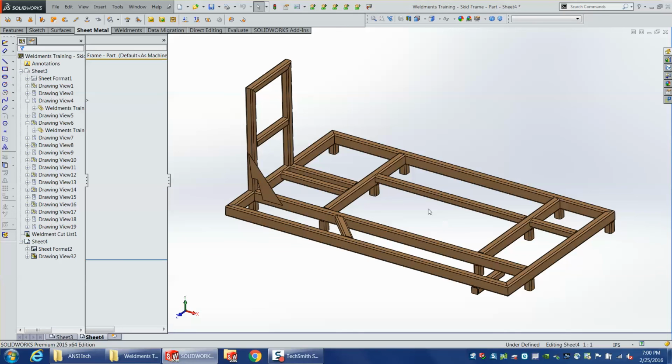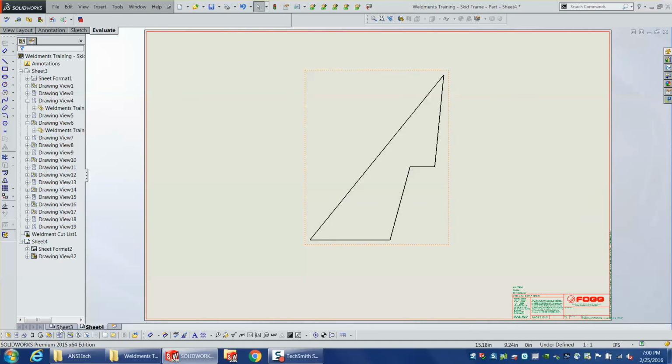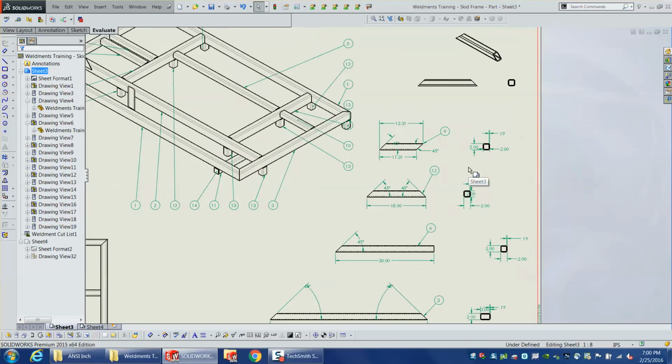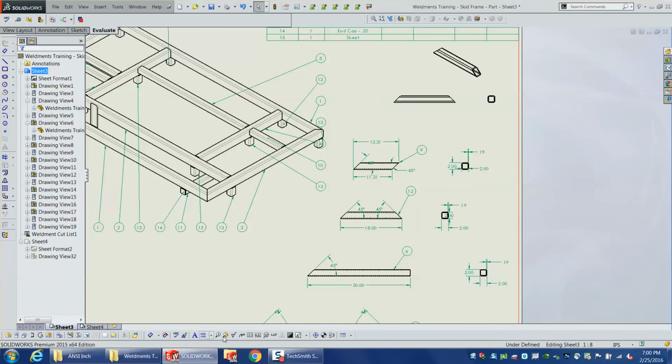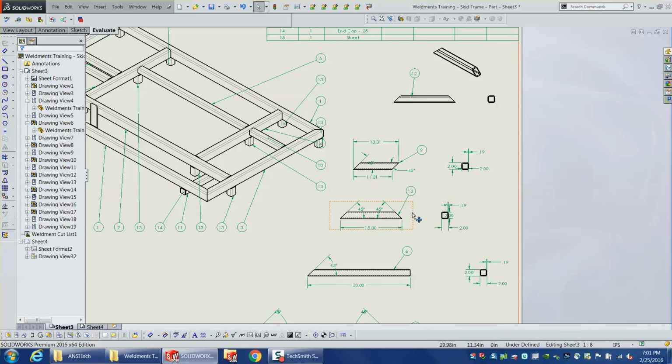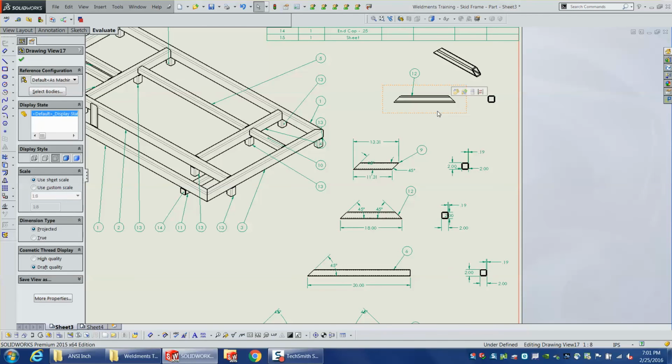So here's one more trick that I actually learned today, and I don't know why I didn't know this. When you have to delete your view, and you say, oh man, all my dimensions I have to re-put on there because this got tilted, if you remember that discussion, you can actually drag your dimensions right from one view to another.